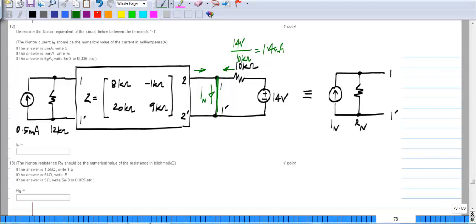So if I use the 2 port notation, let me do that. This is V2, which I have set equal to 0. So this is I2, this is V1, and that is I1. All I have to do is to write out the equations and eliminate the variables. Okay, first of all, I have the Z parameter equations. By the way, sometimes it may be convenient to convert the Z to Y and so on.